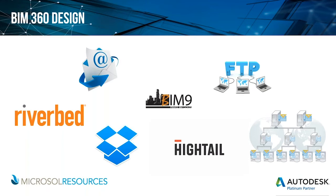On one hand, you would be able to get the files across, but you wouldn't be able to work simultaneously in real time. If you were using Revit Server, you could do that, but it was really only a site-to-site option. So for example, if you have an office in Los Angeles and another in New York, Revit Server worked well for that, but it was not really ideal for working with third parties. The other solutions all basically involve taking an entire model and sending it across.